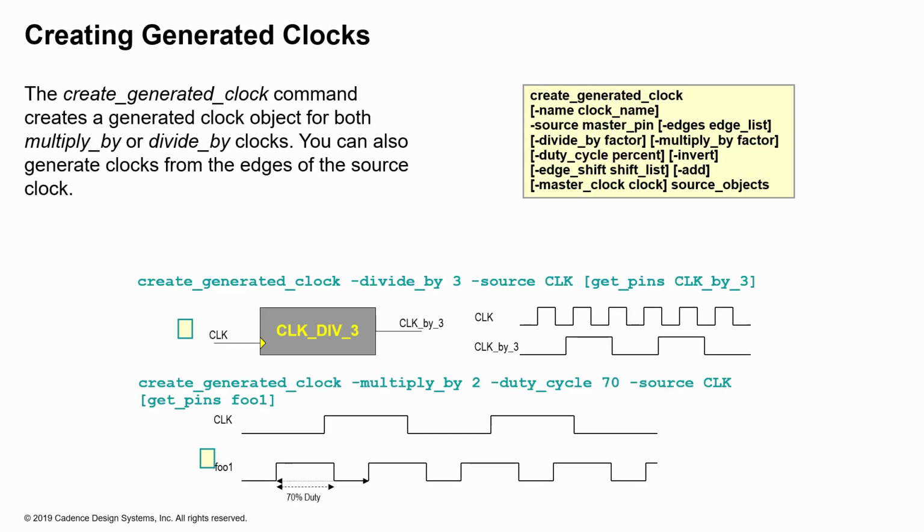Generated clocks are helpful when you want to model a particular clock and inherit all the properties of the parent clock. So basically any uncertainties and things like that that you need to inherit, you can actually inherit from the master or parent clock. The other advantage of generated clocks is that when you have weird numbers or weird divisions that are happening, like 1/3 or something like that, the floating point calculations are actually harder for certain tools to do, and therefore some kind of approximation is needed. But in the case of generated clock, you don't need to worry about such things, because you're just implying that it's 1/3 of a master clock or something like that, and so therefore it's easier to unroll the clocks.